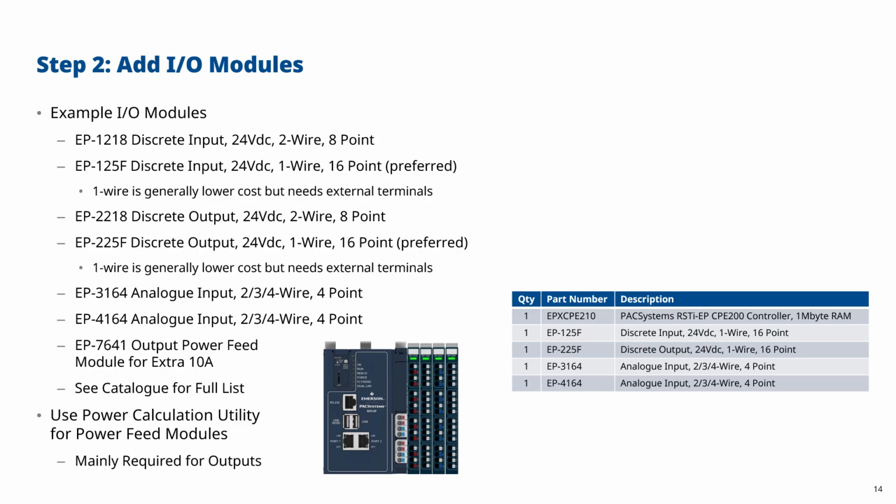So you could multiply your 128 by 1.2 to get your 20% spares and then divide that by 16. Or you could do your divide by 16 calculation first and then multiply the 8 by your 1.2. So for 20% spares on 128 inputs, that would typically be 10 modules rather than the 8 that you really need.